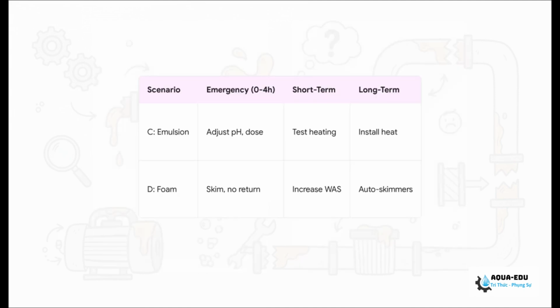Now, things get a bit more complicated when we face emulsified oils. If the oil is tightly bound in the water and simply refuses to float, you absolutely must run lab-scale demulsifier tests in your cylinders. You have to find the correct chemical break before that sticky, stubborn emulsion completely clogs up our entire piping and manifold network.